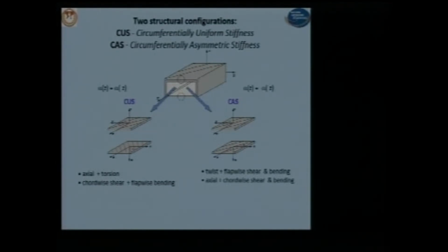If we put something like this, this is the localization of the reinforcing fibers. Why is this important? Because in this configuration, this is very specific. We have the highest possible coupling between bending, flapwise bending, and twist. If we put one actuator in the next step, we can bend and immediately twist the structure. And this is the best configuration. We tested this.